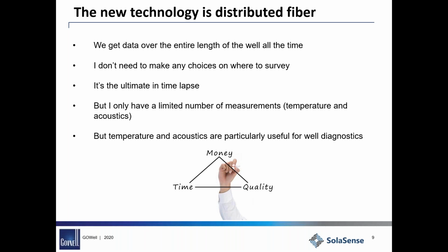If I looked from trace to trace to trace, then there would be variations within that temperature, but I would always want to run a memory or a surface readout pressure temperature gauge at the bottom of my fibre anyway, and that helps me normalize any perturbations in the distributed temperature survey and correct those for any anomalies.